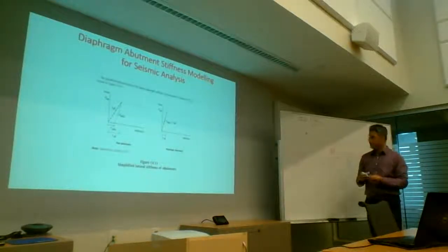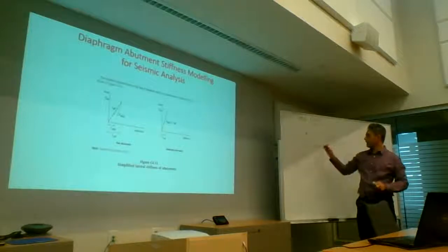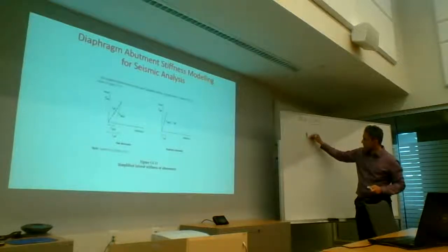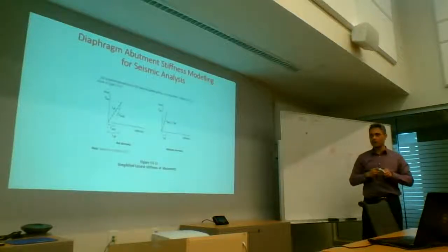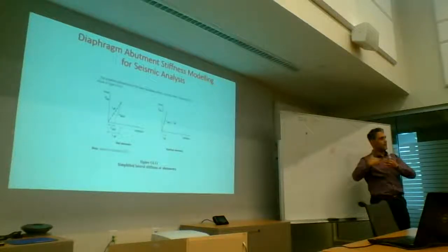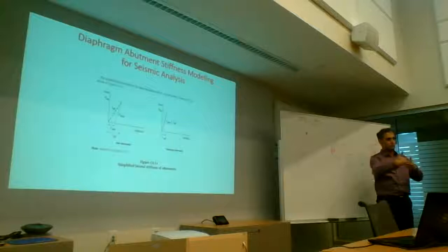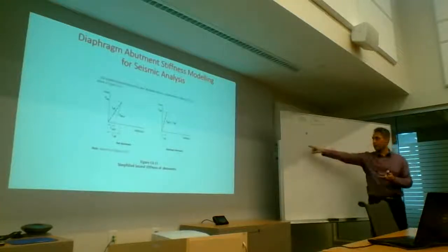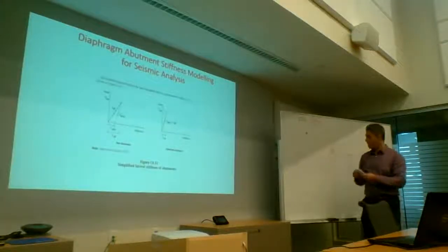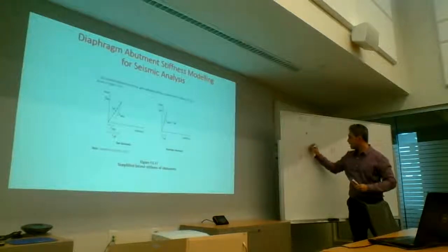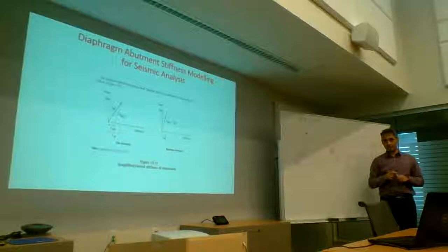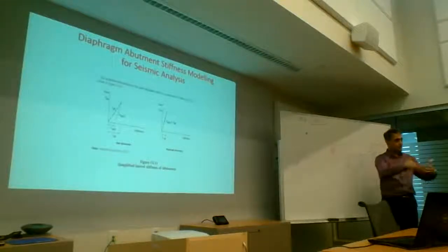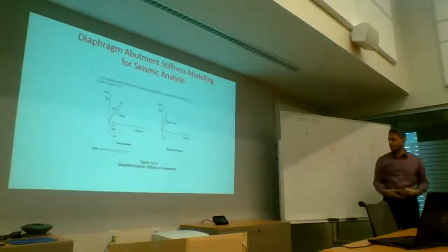So what do you do? You then say, okay, I'm going to correct for it. I'm going to use this displacement, but I'm going to use this force level because my force level cannot go beyond that. My soil at the back is yielding that. So I cannot provide more force than this force. Then I do my second iteration and I end up here. Now I've softened the stiffness. I'm going towards a more realistic behavior.